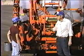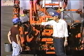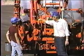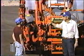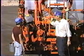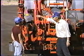Come to the back of the truck, bring our hose, put the hose on the tanker, hook the hose up to this top valve here. We call this a loading valve. It has a screen just behind this valve to catch the rags or whatever that might come out of this hose that we're using or out of this transport. We've got the pump in reverse. We open the transport valve. Now we open this valve.